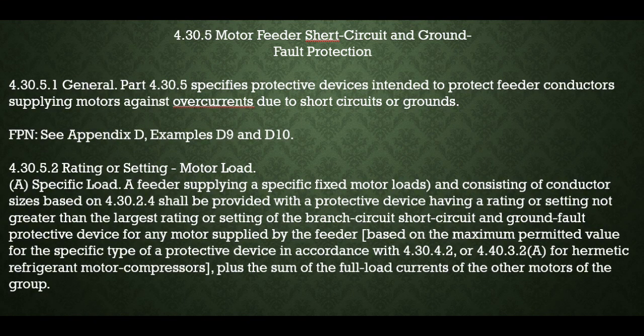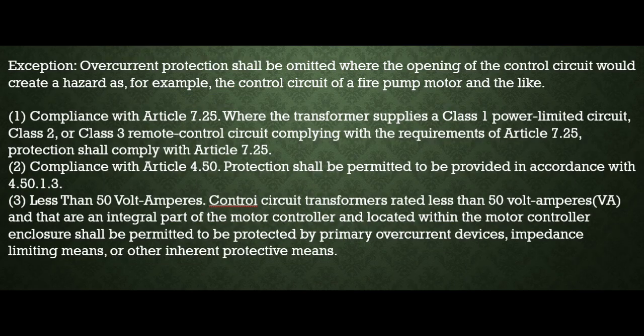Nag-cover na po ni siya sa motor feeder protection. Part 4.30.5 protects feeders against overcurrents from the short circuits or grounds. For a specific motor load, ang feeder protective device rating should not be greater than the largest branch circuit protection rating plus the sum of the full load currents of other motor in the group. So next slide, it covers control circuit protection.